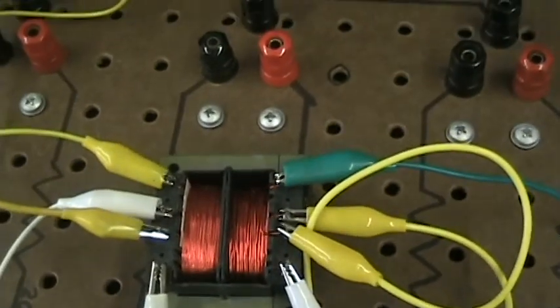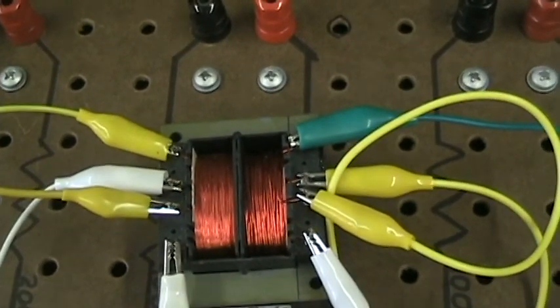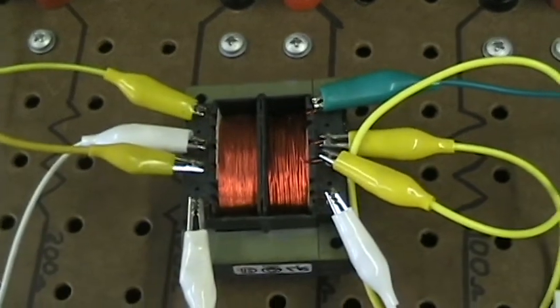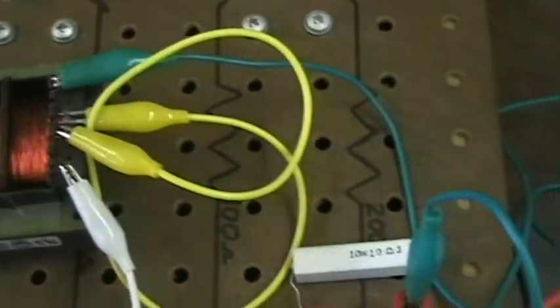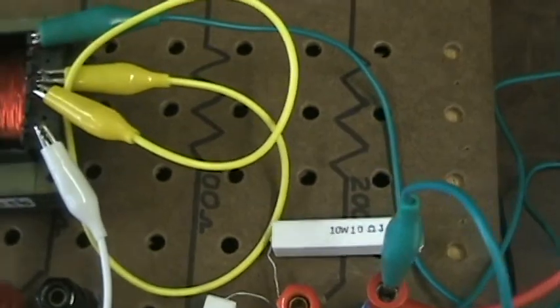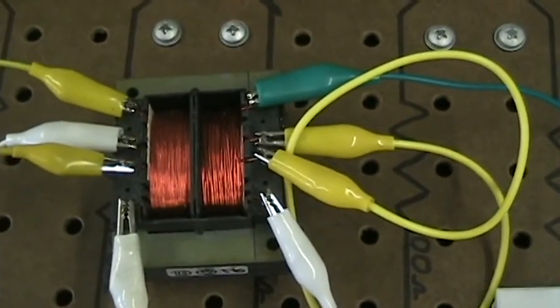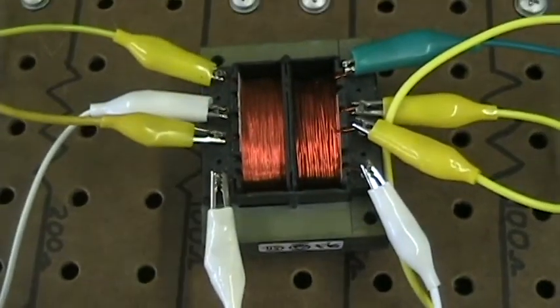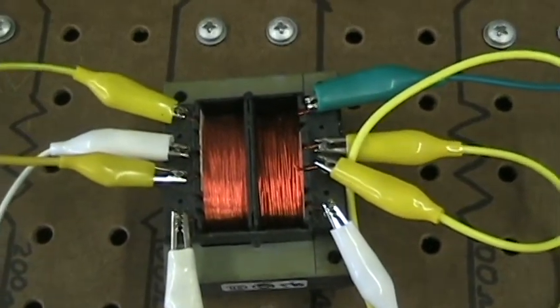And that's why you should use all windings on the transformer when you activate it. Even if the output voltage is the same as previous, 20 some volts, 20 to 23, we get better performance if we have both of the primary windings in parallel.